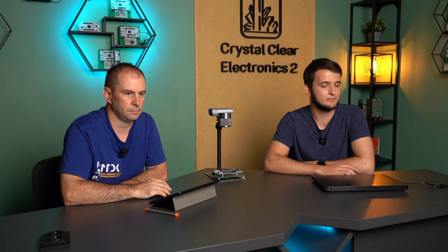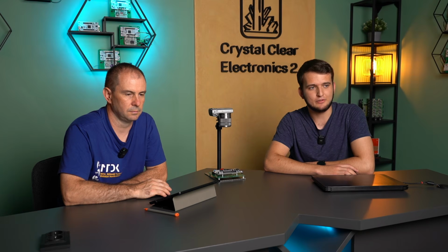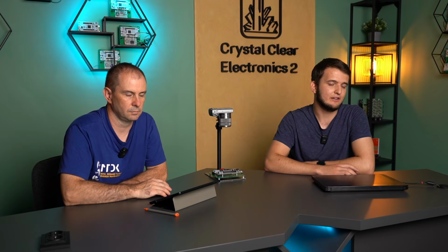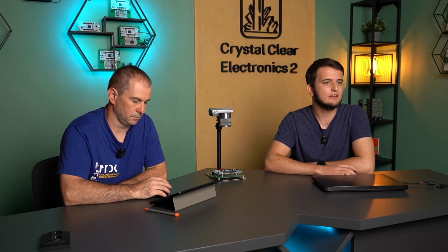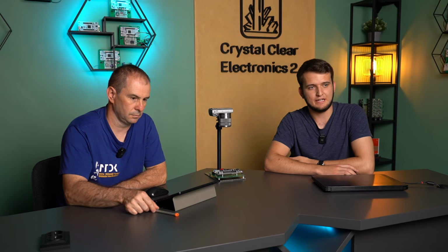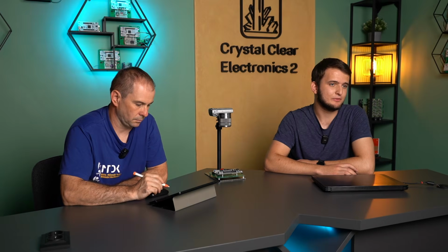The first one I'd like to mention is the UART, or Universal Asynchronous Receiver/Transmitter. This unit is responsible for managing asynchronous communications, usually inside the controller. UART is available on several legs. For example, UART TX can be found on PG14, and UART RX can be found on PG9 on the development board. These are mostly connected to hardware interrupts, so that the processor can be easily notified when new data is received.